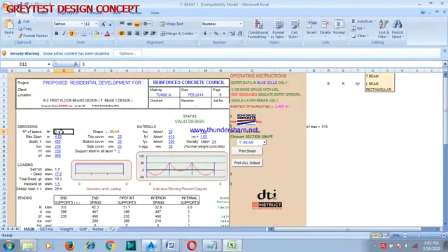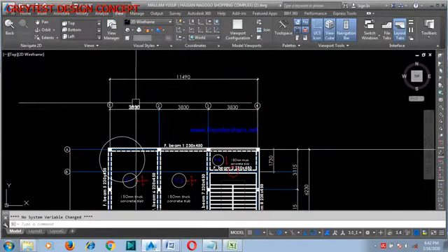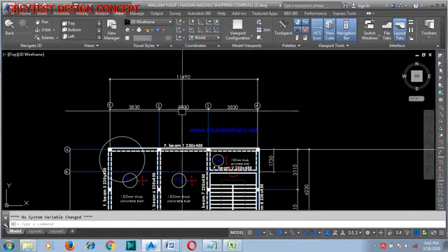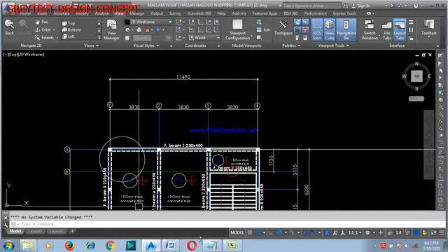So here we type 3. You can see there's 3 there already. It's now asking what the maximum span is. You just pick the value of the maximum span. It happens here that this whole beam actually has the same span. It is 3830.